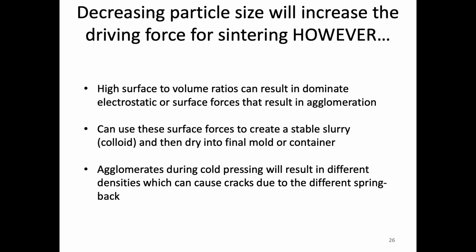So clearly, if we have more and more surface area, that's going to drive this reaction more and more. And so we can increase the driving force for sintering. So a lot of times what people do is they make nanoparticles of these ceramics, and they find that they can sinter at lower and lower temperatures and get the same result. And so this is obviously something that is good. We want to do this to increase the driving force. But I will mention that there are some negatives to this.